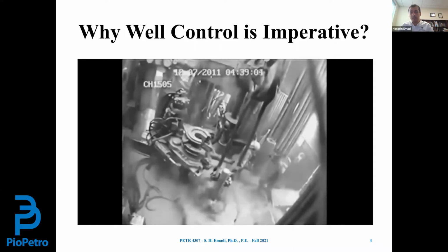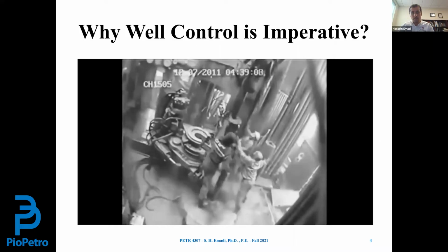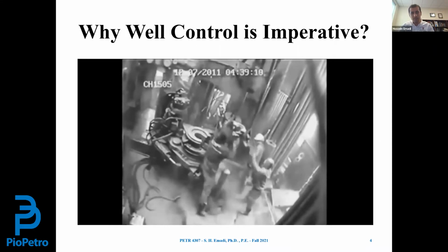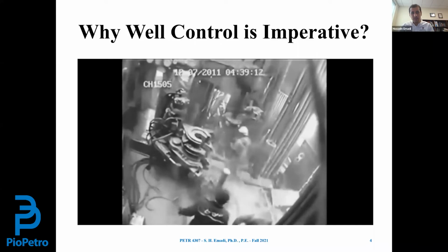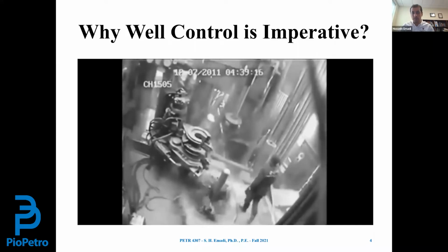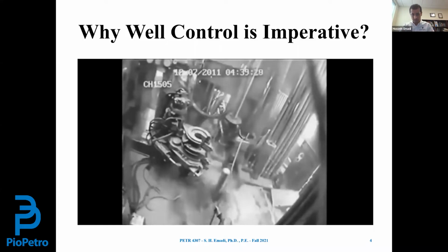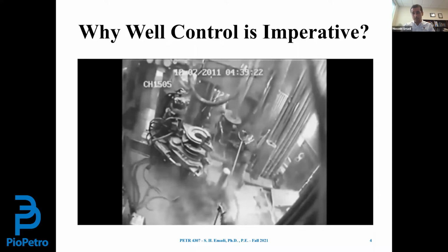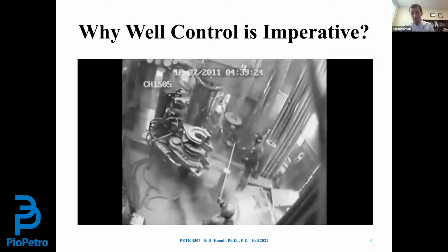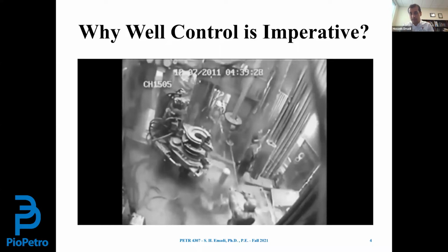So it's almost 1 minute, or 30 seconds. And now you can see more and more formation fluid. I mean, the drilling mud at a higher rate is coming out of the wellbore, meaning that progressively formation fluid is entering the wellbore at an increasing rate.